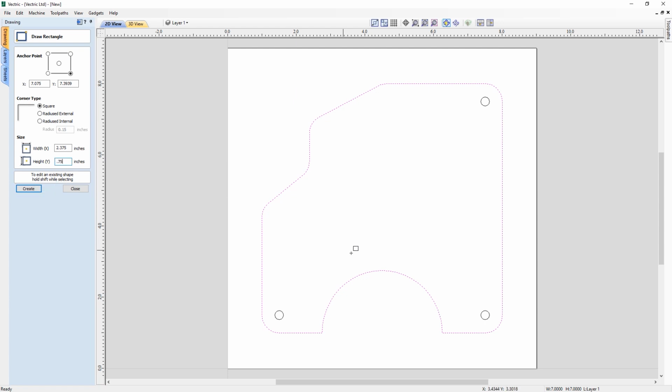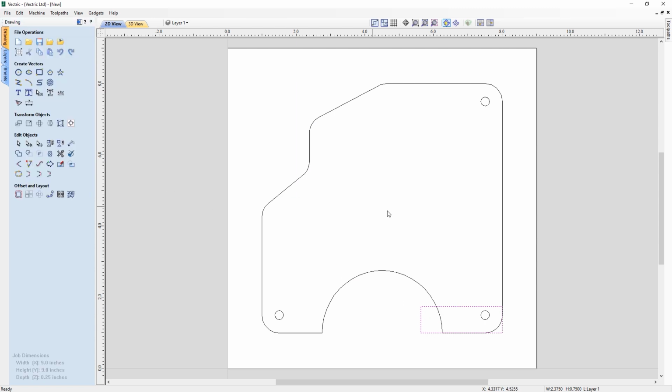Instead, what I'm going to do is move my mouse across, hover over this bottom line, hover over this vertical line, and then move through the intersection point of those, and the software correctly identifies that as a snapping location. And by clicking, I can now create my rectangle here. I can close off this form, and now I know that I need to move this up by 1.5 inches.